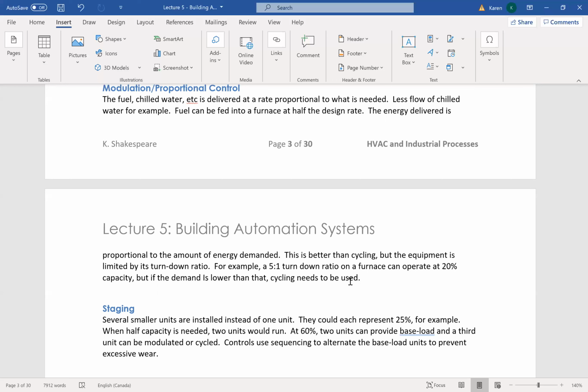So use unit A and C, then use unit B and D, and all of that equipment has a duty cycle that is lower than it would be if you had spent that same amount of money on one large unit that has a massive duty cycle and it's always being used. So that's common in the HVAC world, especially with chillers.